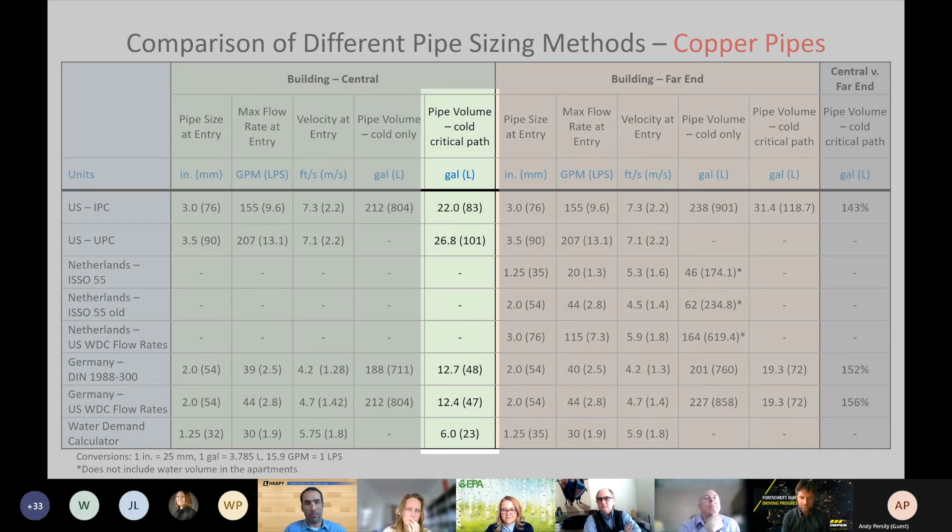So, obviously, the lower the number, the more likely you are to have fresh water sooner. Obviously, out of 45 apartments, more people are going to be using water, so it's not 22 gallons for just that unit, but that's the extreme case of you're the first person in the building and no one else moves in for 6 months. You got to drain 22 gallons to get your water to turn over to fresh water from the street. Actually, Jeremy, it's probably worse than that, because it takes more volume for it to actually fully turn over, but it's a minimum of the volume in the pipe.